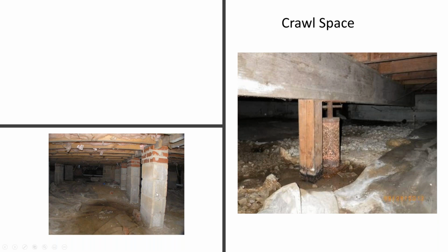This has a bit of a lean to it, which is kind of scary, but at least it's on concrete sitting on dirt. Ideally, whoever tried to fix this should have just simply either dug it out and poured a footer out of concrete, or bought a few stepping stones that you can get at Lowe's, set them on top of one another, and then set these on top of it so that they're up out of the water. That would have alleviated this problem, because now this is going to sag and droop.